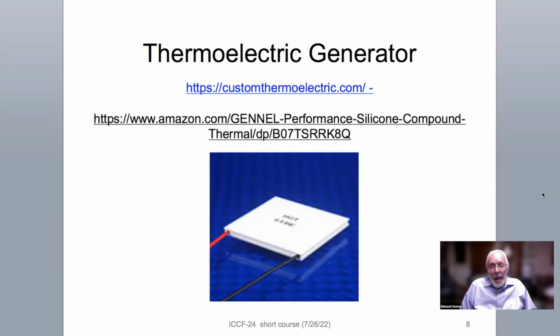Now, the bonding material has sufficient stickiness that if it's applied uniformly to the thermoelectric converter, it will allow the thermoelectric converter to stick to the metal without any additional efforts to keep it attached. And that's very convenient because there are occasions when one of these may go bad or several may go bad and it's necessary to replace, and that's easily done if the only bonding is with this thermal paste.